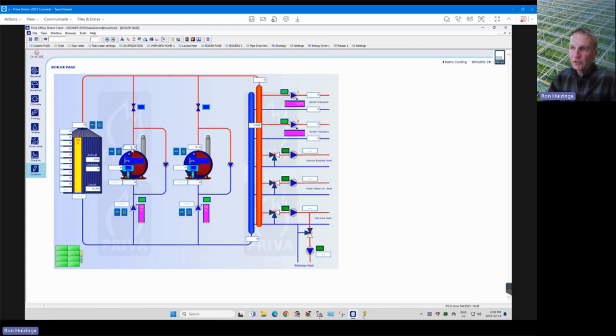And then at that point, you should get 90 out here. But if we start getting 91 out here, then we start calculating this down to say 79. And to get 79, we have to speed up this pump a bit to get a little more cold water to get that temperature down to 79 to get 90 coming out. So that's how this calculation works to speed up and slow down this pump.